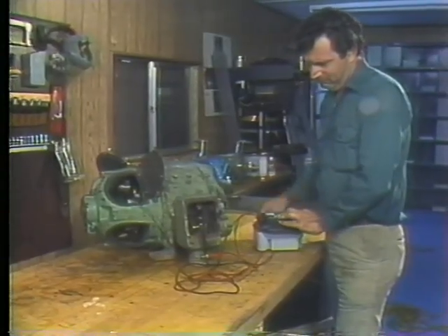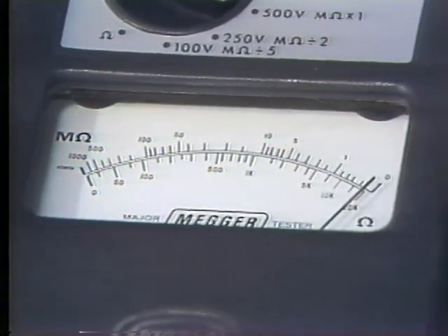All right, let's check. Well, this motor is grounded. If all you had to do was report whether or not the motor was grounded, you could say yes and be done. But if you had to repair it, then you'd have to locate the grounded part or parts. There's no guarantee there's only one. Here's where you use the process of elimination to save you time and prevent unnecessary confusion and error. To go any further, you have to break the circuit up and test one part at a time, eliminating the parts that are good so you can work on the ones that are causing the problem.